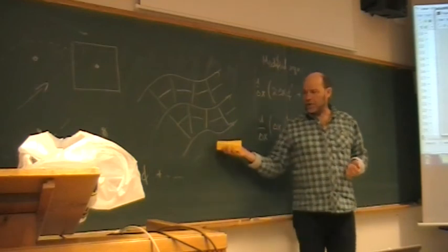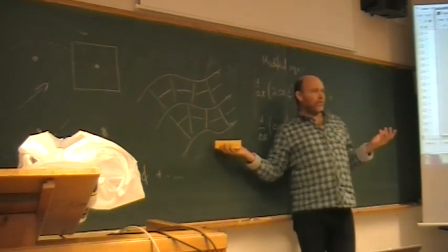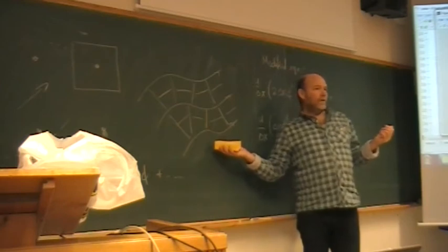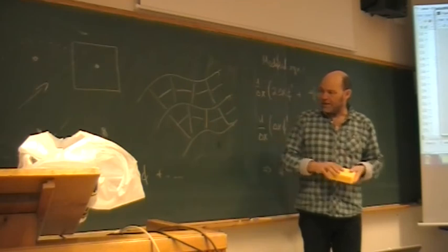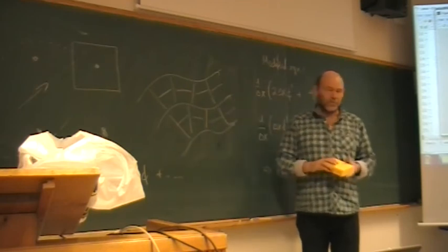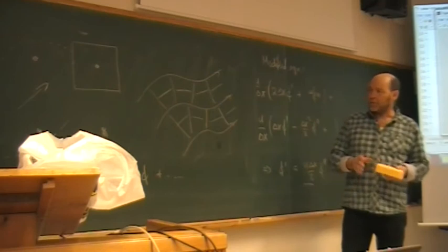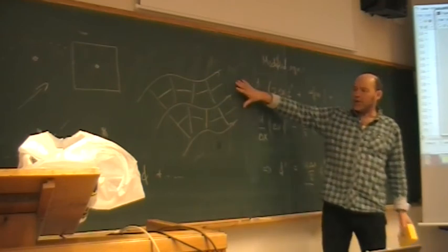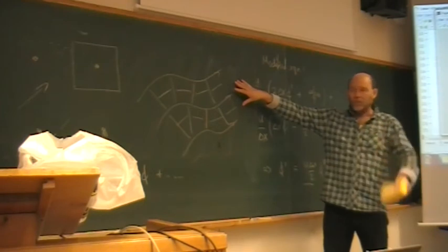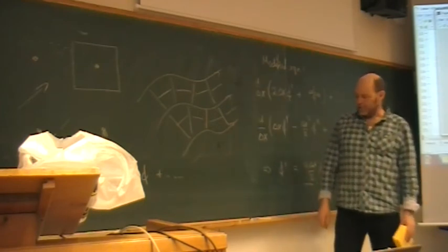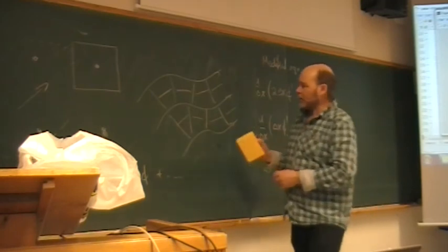Typically what people do here, you simulate first using potential theory. No viscosity, no friction forces. Very cheap solution, it's actually just a solution of the Laplace equation. And then you have the streamline picture, and then you use the streamlines to create the mesh. And then you fire up Navier-Stokes. So that's one way to create a good mesh.